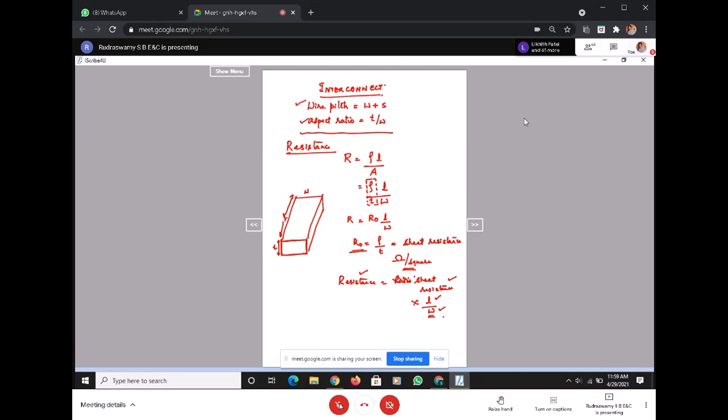These wires not only provide the delay, but they also give rise to crosstalk, as I said. The moment I have two wires which are close to each other, there will be crosstalk. If this is passing some information, it will in turn interfere with the other wire. It will induce something into the other wire, and that's what we mean by crosstalk.